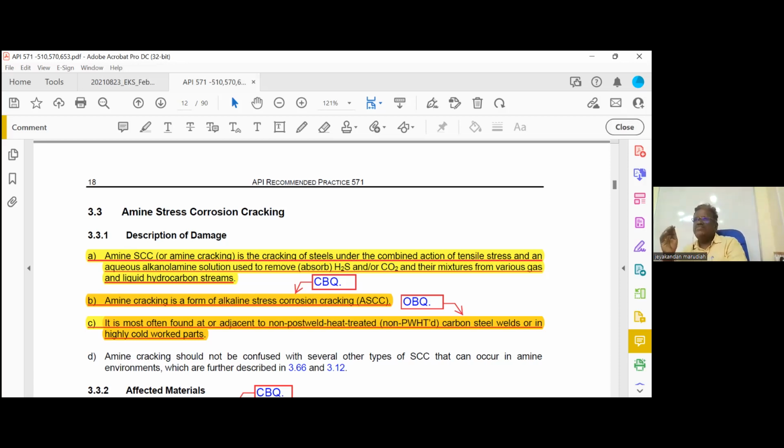These are the NDT. Now the preventive action for stress corrosion cracking means you have to remove the stress. How will you remove the stress? PWHT is the preventive action. For stress corrosion cracking, 1175 degree Fahrenheit, you have to do PWHT. Caustic, 1150 degree Fahrenheit. You remember B31.3 PWHT is 1100 to 1200, a range they have given. Here they have given some exact values. So these are the common things.